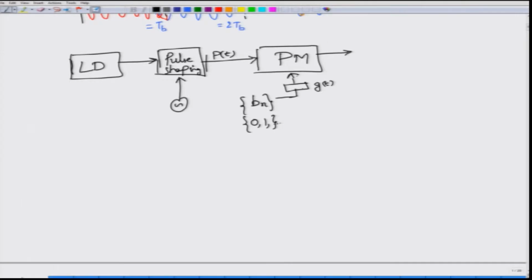It will also multiply it by a certain constant, right. You need to multiply this one by square root of 2 Es by Ts, or you can adjust the amplitude or adjust the power of the laser diode in order to get that power value of 2 Es by Ts. Okay. So, you can either adjust it by the laser diode, or you can adjust it by the bit sequence map multiplication, it does not matter whichever way you do. What you get here is the BPSK signal.